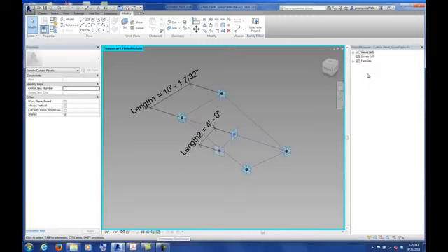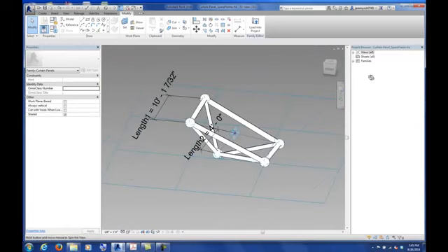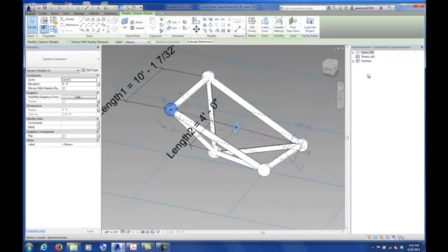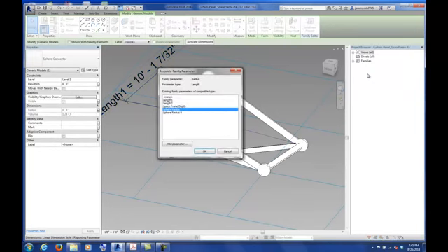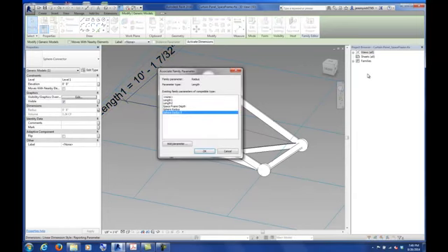All right, if you're not here, just kind of follow along. I'm going to wrap it up, and then you guys can go back on the video for part of the homework. I'm going to reset all of my temporary elements here. And I'm going to do the following. Remember, all of my spheres right now are related to that radius parameter that says sphere radius. I'm going to do one more here, the one down at the bottom. I'm going to change that radius and make that equal to sphere radius B.